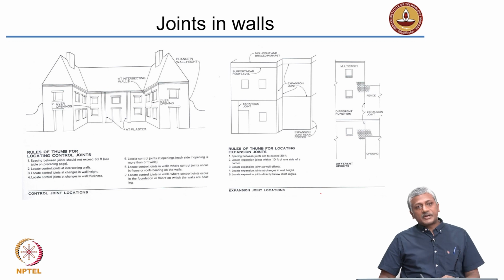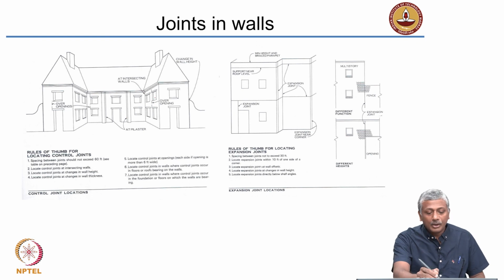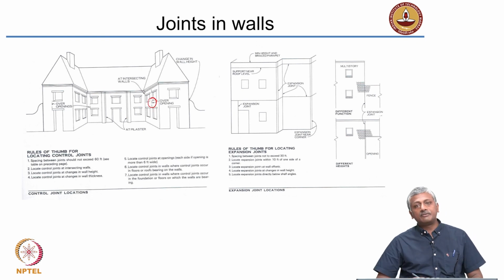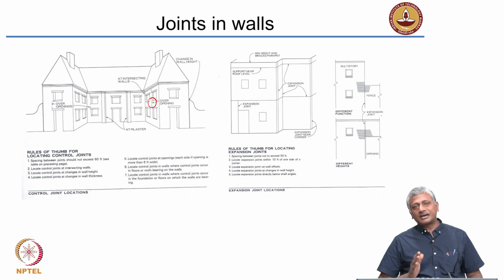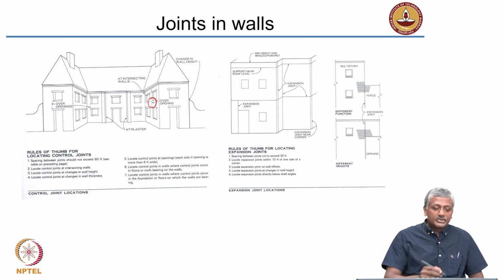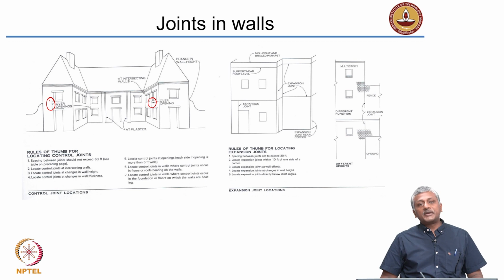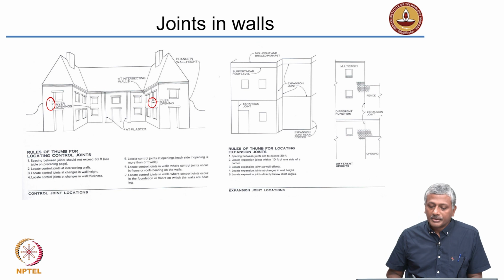Now, again the expansion joints are not only provided for running length, you may also want to provide them wherever you are seeing window openings, because one of the common features you will observe when you see your own house, for instance, is that many of the cracks are emanating at corners and wherever the openings are. So, to avoid such cracking and avoid failures, generally your joints may need to be provided over such regions. All you are simply doing is providing some free movement of the different structural components in your construction. Okay. So, those are some examples.